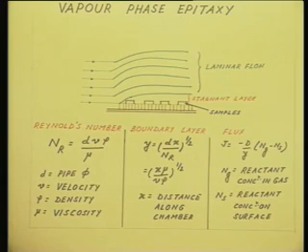So, you see across this boundary layer, on one side I have Ng, that is in the gas stream, and on the surface I have the concentration as Ns. Therefore, the concentration gradient is given by Ng minus Ns divided by the thickness of the boundary layer. So, the flux is going to be proportional to this, and this is the proportionality constant d, or the diffusion constant also, as sometimes it is called. And the negative sign signifies that the flow is from the higher concentration side to the lower concentration side.